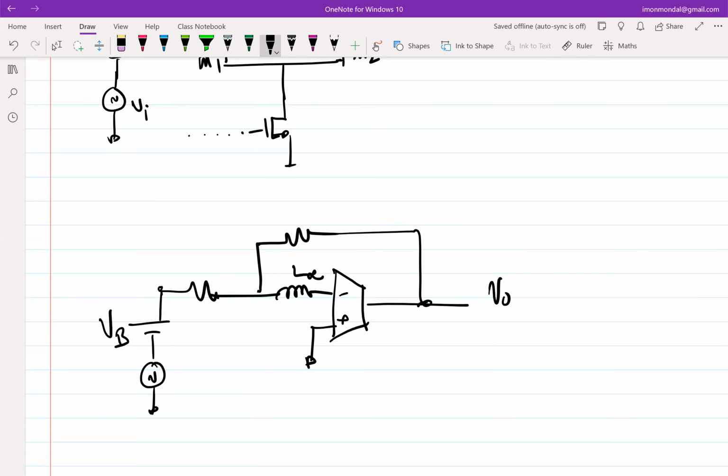But then how do you figure out what your loop gain is? In our case, we were applying an input here, V test, and observing the voltage here, V return, while shorting this, obviously. So you'll have to apply a V test. How do I apply a V test without disturbing the operating condition? This V test has to be incremental, right? So you have a small incremental AC source in your simulator.